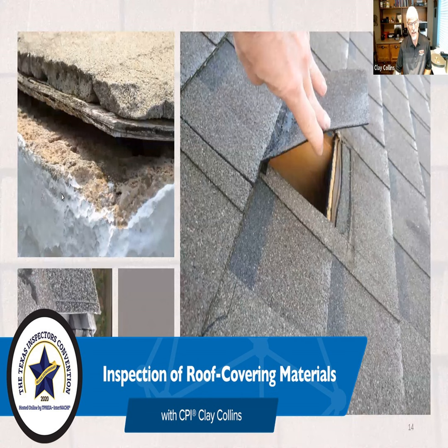Now, a lot of times we'll see a spray-on silver paint. Sometimes that is used to encapsulate scorched wood in case of fire. And sometimes it's intended to be a radiant barrier. I would suggest that you don't state that it's one or the other until you've been very careful to see what it might be covering.